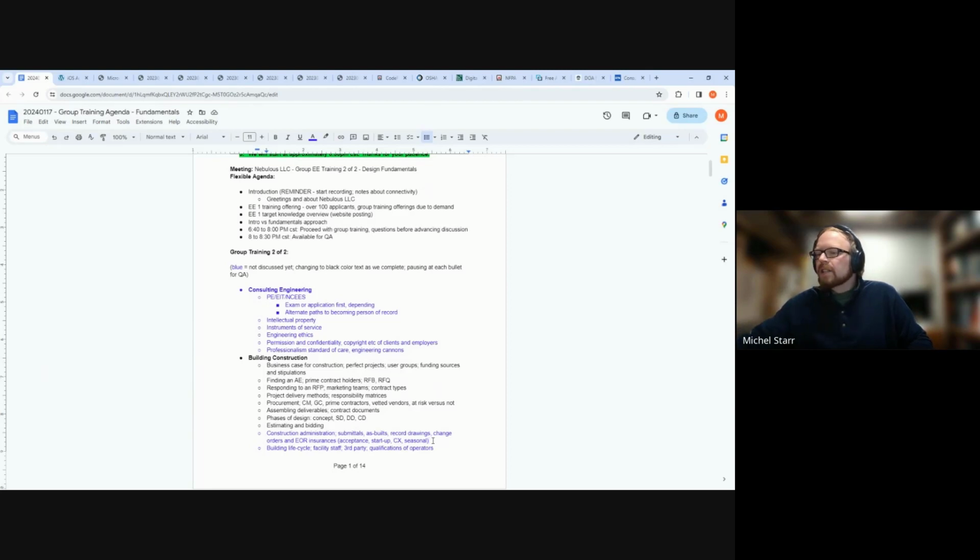The installation isn't just install, there's acceptance testing for a new installation, voltage levels for testing of cables, and would be one example as a difference to maintenance testing. Startup, so maybe that involves the manufacturer's representative if the specifications were written or edited to say that. Maybe it's just a contractor. Maybe it's not big enough to have a startup activity.